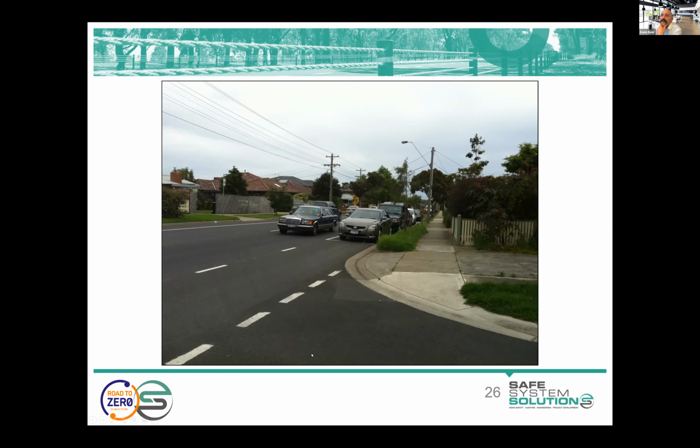Okay, so lots of things coming in. Jamie, they're a great group for answering these sorts of questions. So we've got some requests to remove parking. So that's obviously going to open up sightlines. There's also some discussion about curb build-outs, curb out stands, building the curb out to open up those sight lines, moving the stop line forward, or the give-way line, the hold line forward.